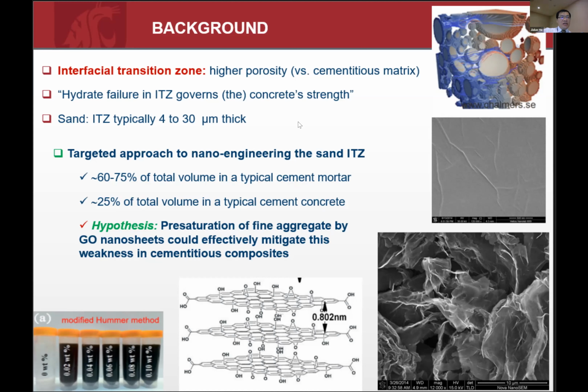You can see the graphene oxide, because of all the surface groups, is highly compatible with water. You can dissolve as much as 5 grams per liter, and you can have about 10 grams per liter as a suspension, and it will look like a dark ink. So there's no dispersion challenge like carbon nanotubes or carbon nanofibers, because there are many hydrophilic groups on the surface.